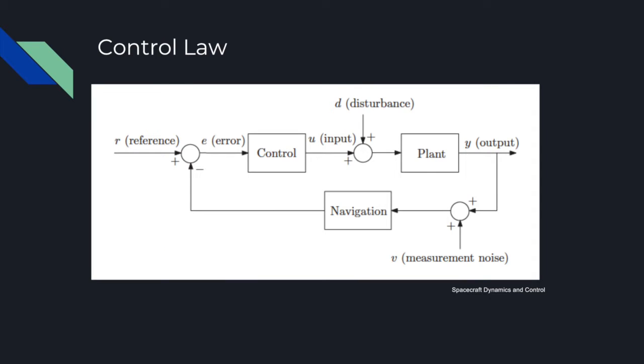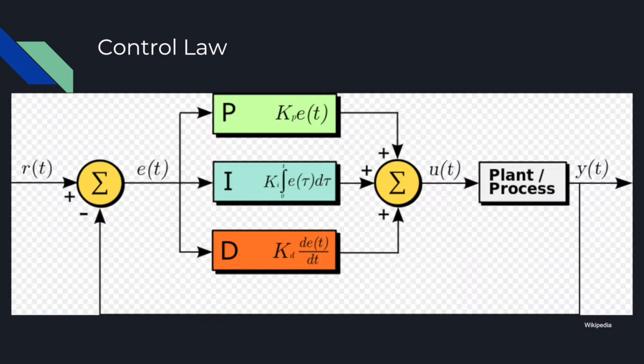Since we are trying to maximize the efficiency of our system, it is necessary to apply a measured amount of torque based on the error in our angle, and use a critically damped system to ensure we don't spend more energy than necessary to reach our target orientation. For this reason, a PID controller would be the most efficient. According to Wikipedia, a PID controller is a control loop feedback mechanism widely used in industrial control systems and a variety of other applications requiring continuously modulated control.